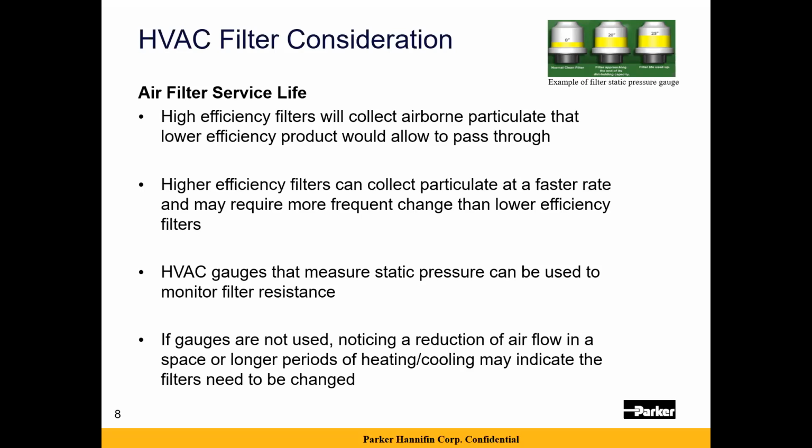If you're not feeling as much air coming through the supply side of the system, or if you have longer periods of heating or cooling going on, or you're not getting enough cooling in a space or heating in a space, that may be an indication that the filters are ready to be changed.